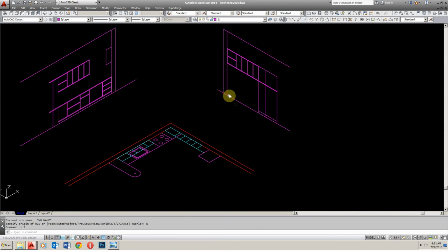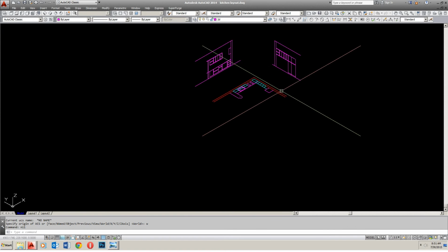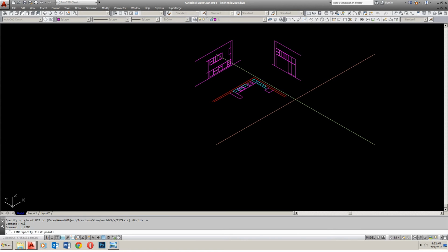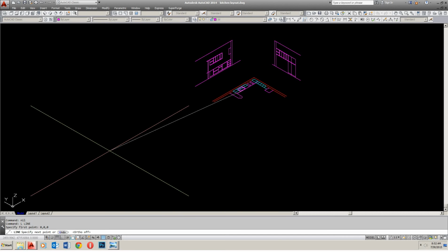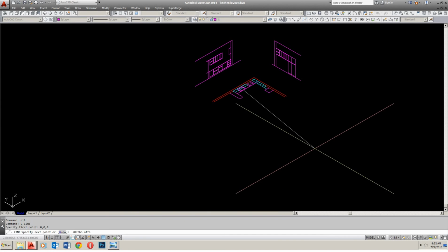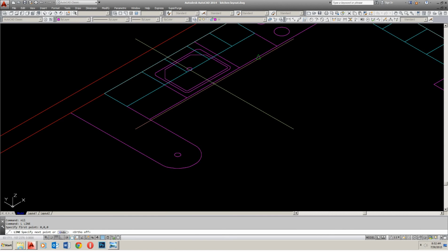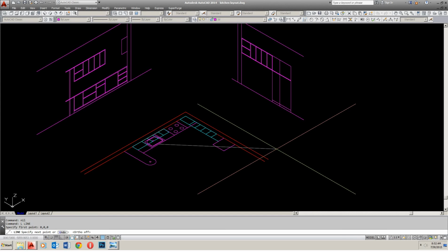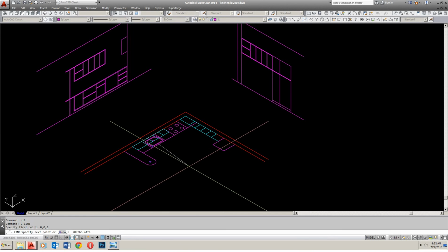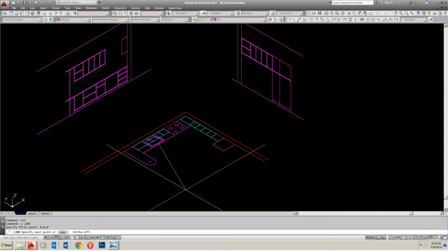Let's start modeling this. First of all, make sure that you draw a line from the 0,0,0. That's the origin. Make sure that line is inside your model, somewhere that starts from inside your model. See, my 0,0 is at this point. This is important. If it's too far away from the origin, V-Ray has problems, I heard.